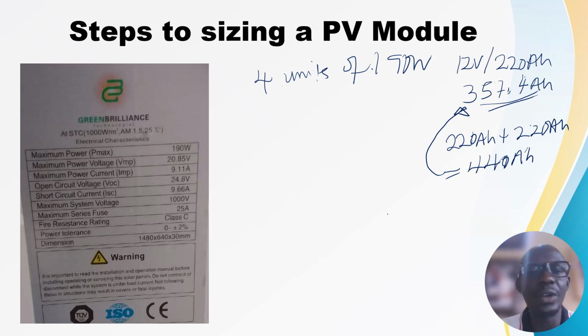You can connect your panels in parallel and series, and intelligently the MPPT will do justice to any of the connections, but you can't do that on PWM. Apart from that, PWM is not efficient, it wastes energy. But the MPPT will track the maximum power you need to charge your system. So, for instance, now I need 4 units, and you equally need a good current.